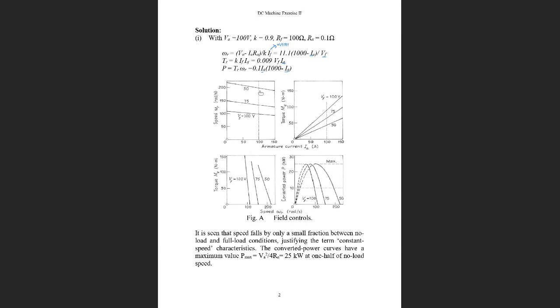So this gives you a hint that if you would like to make the motor speed higher, you can choose a lower field voltage. A lower field voltage gives a relatively higher motor speed. When you want the motor speed to be relatively higher, you have to choose a relatively smaller field voltage. Generally, it is a linear relationship between them.